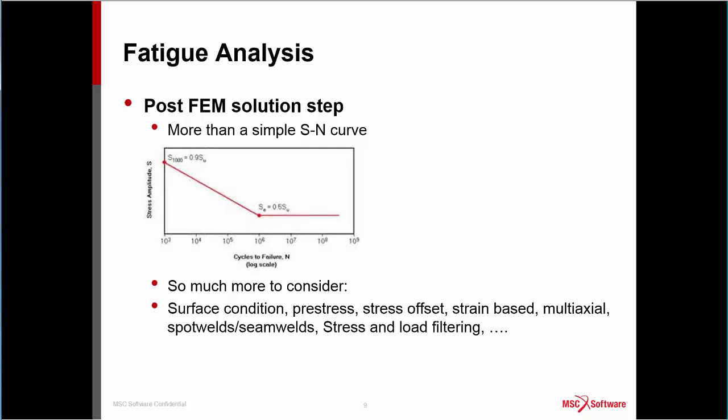After that, it becomes more involved, and at that point, you want to start considering using a code to do this. If you're going to look at multi-axial, spot welds, seam welds, or what they call EN analysis, which is strain-based, you have to do a computer calculation for this. Also, these FEM models are so large that the volume of stress that comes out makes it almost mandatory that you filter things.